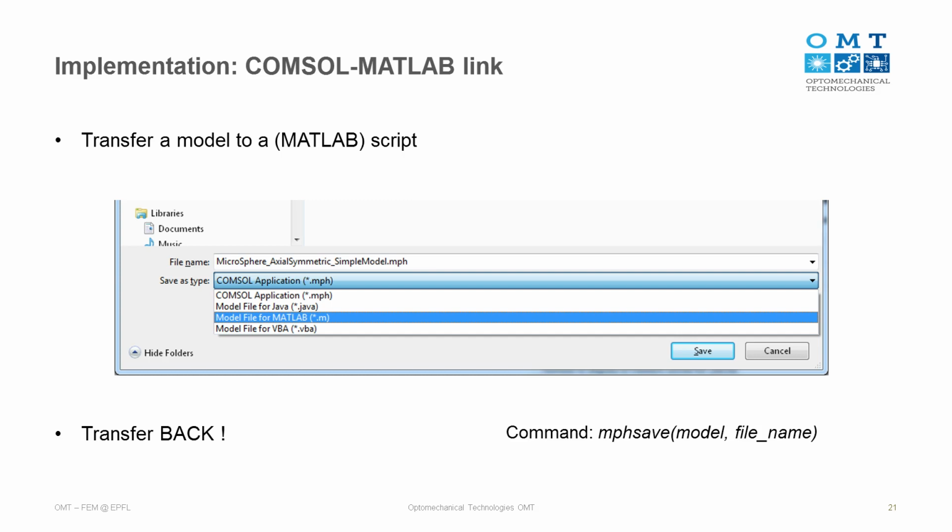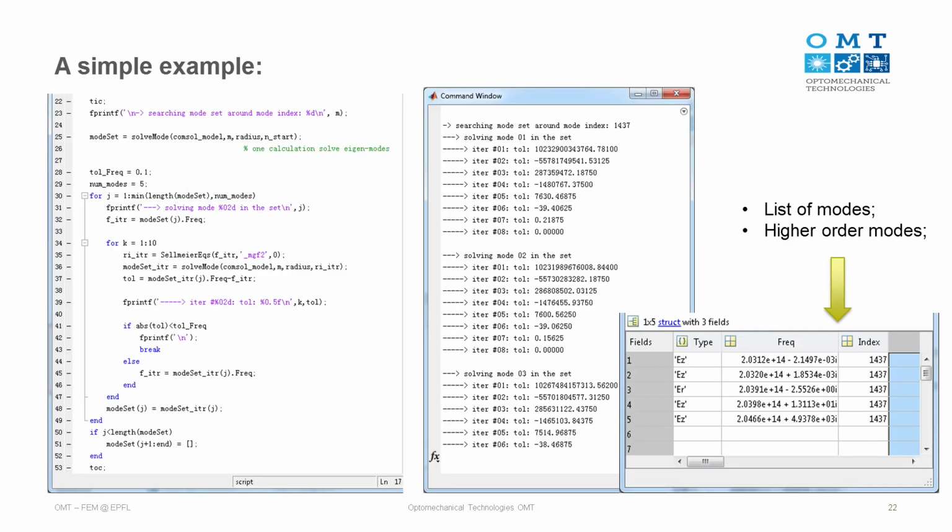Yeah, we have a simple example there. Also in the folder, under the subfolder axisymmetric, you would have the MATLAB link. You have that folder? Okay. You need to open it, because there you only find MATLAB scripts. You need to open the runme.m file using COMSOL with MATLAB, not just opening MATLAB.